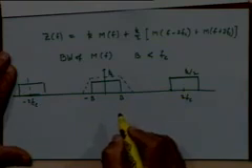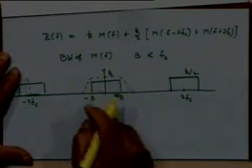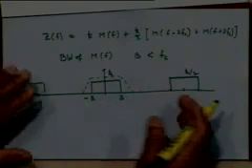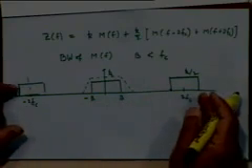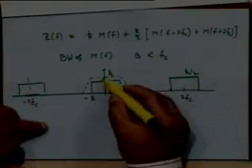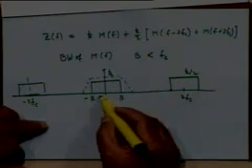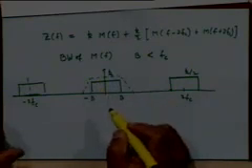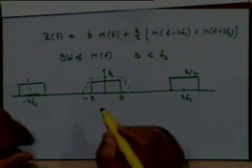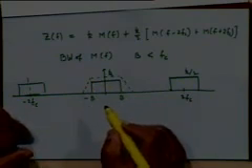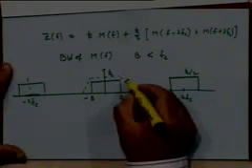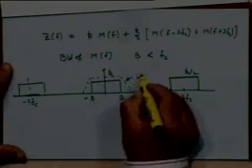You can correct it suitably. So if you have a low pass filter with a response like this, obviously this signal will get eliminated, and what you will get at the output is the product of this frequency response with this input spectrum, and therefore you will just get your M of f back. Is it clear? So that's the low pass filter transfer function.